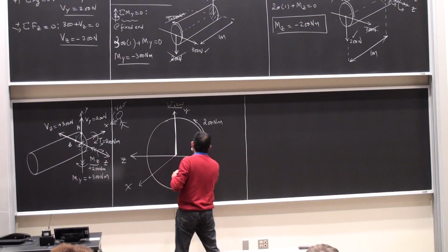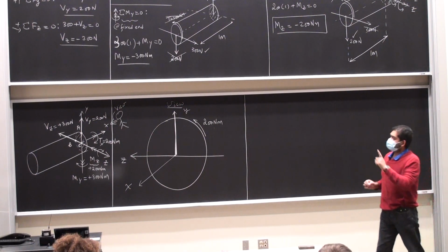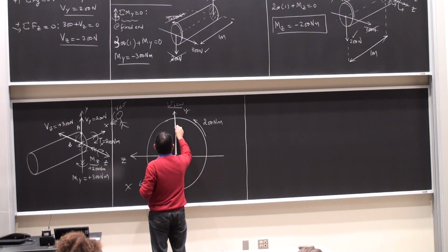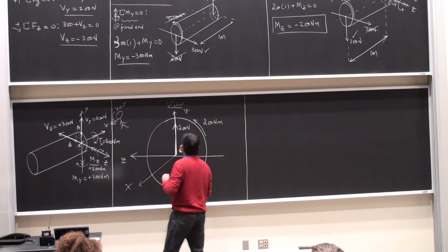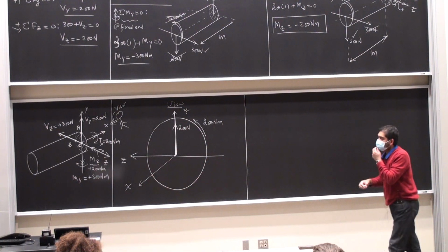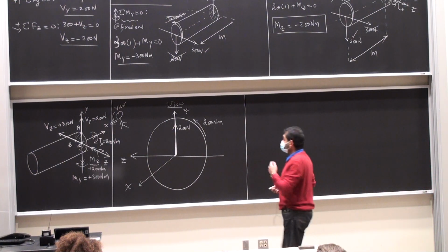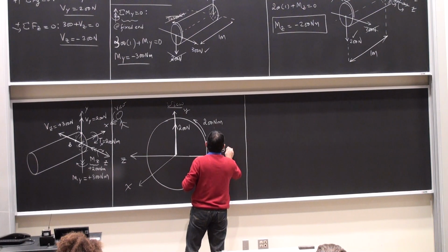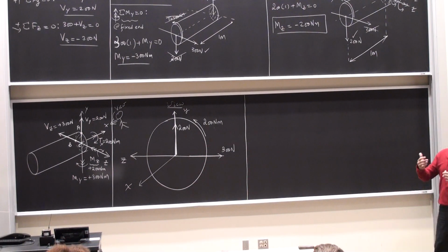Extend these lines. Then the shear force along the y-axis is along the positive y-axis, so I can just point it out that way. Newtons. And then Vz is along the negative z-axis, so I have to mark it out in that direction. 300 newtons.